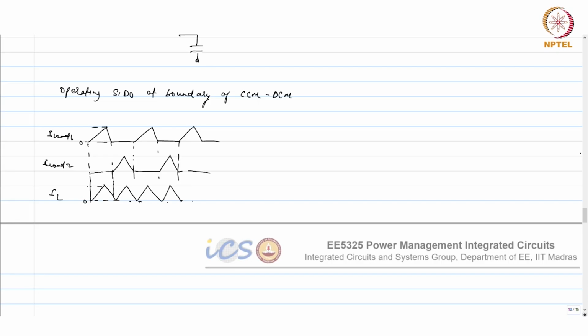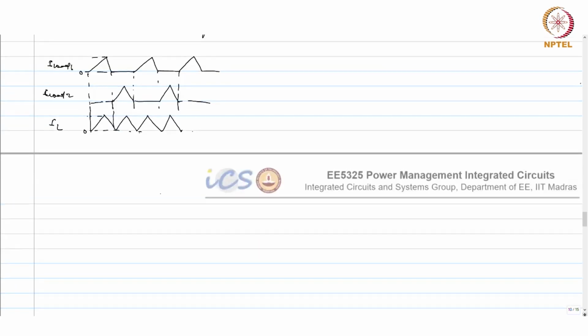So in order to maintain this continuity, you have to change the frequency. If you are not concerned about the switching frequency, then it's fine, and you can always keep the inductor current continuous. So it's similar to the constant on time we were talking about. As soon as it goes to 0, you trigger the next phase, and that will come from your control. The on time will be decided by your V control. Say you are comparing a ramp with the V control, that will generate the on time. So that on time will vary, but it will always get triggered at zero current information.